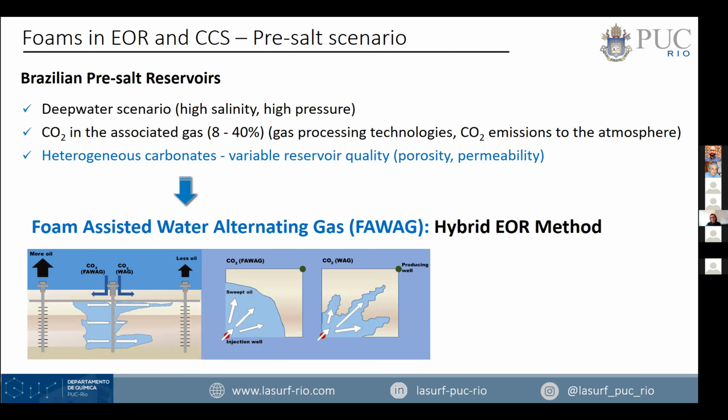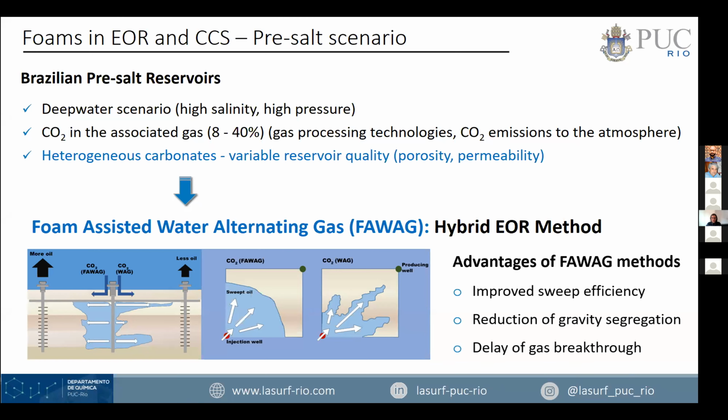And this is a hybrid EOR method because it combines the miscible gas principle with the use of chemicals to form this foam, which is going to be the important fluid here to achieve a more homogeneous displacement. So we have several advantages over the WAG method. It's possible to obtain an improved sweep efficiency, reduction of this gravity segregation, and delay of this gas breakthrough.